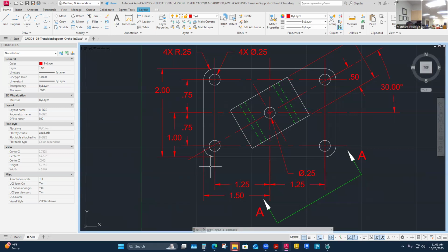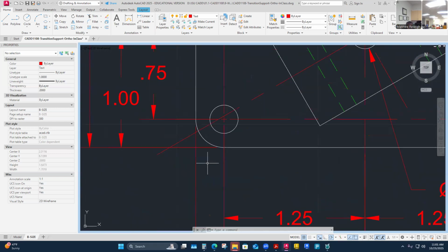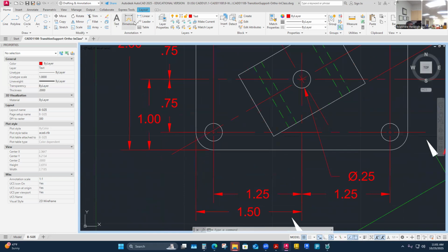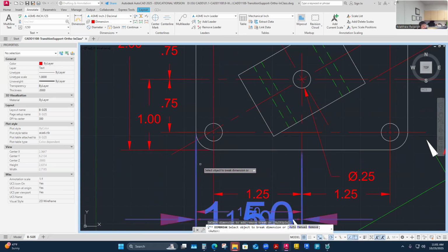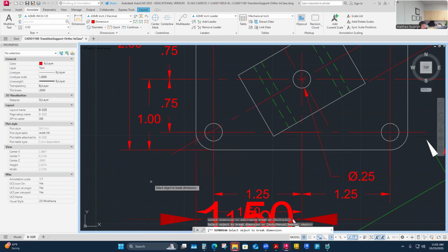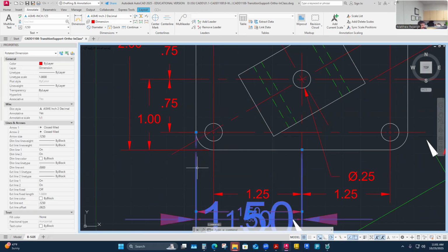And yeah, technically it wouldn't matter which one I broke here. So I feel like you could choose either. Yeah, that's good. Definitely. Because these are both extension lines, one of them doesn't take priority over the other for sure. So whatever one I choose second will be the one that does the breaking, like that. Sometimes I actually like to choose that one, because otherwise I would have had multiple dimensions to break, right? So maybe I chose wisely because I only had one extension line to choose that one first.